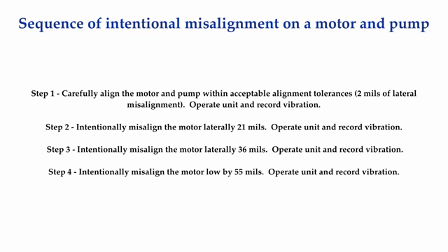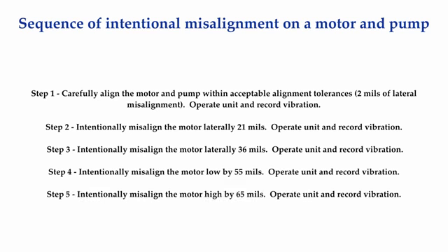Then I put the shims back in and added 65 more mils of shim stacks so the motor was high with respect to the pump. I collected both overall vibration measurements and vibration spectral data. For this tutorial, we will look at just the overall vibration data. The vibration spectral data will be discussed in a tutorial in the Category 4 Shaft Alignment Training Series.